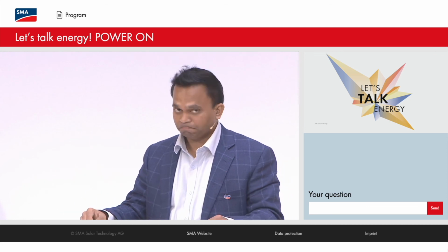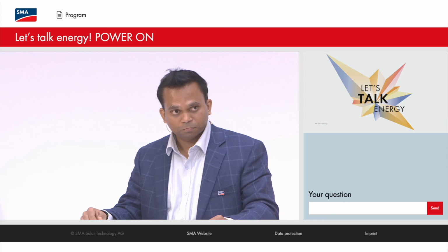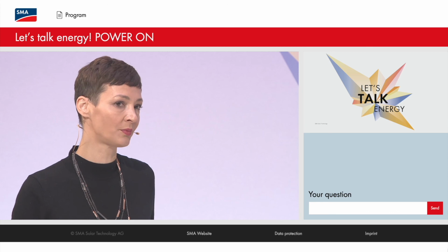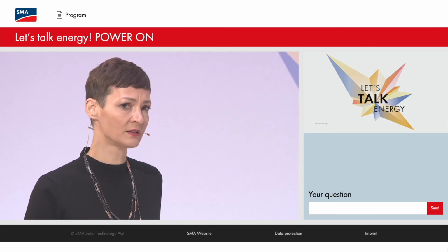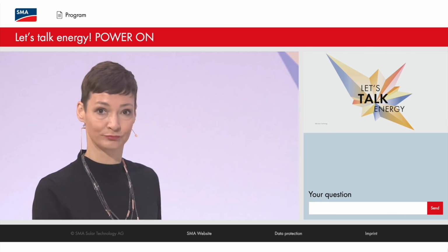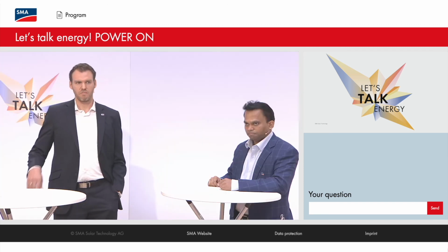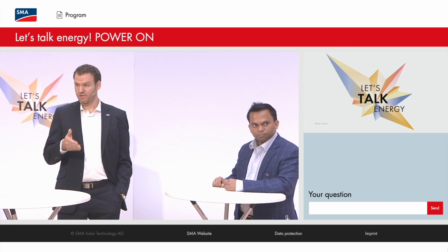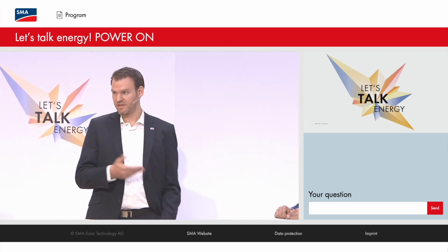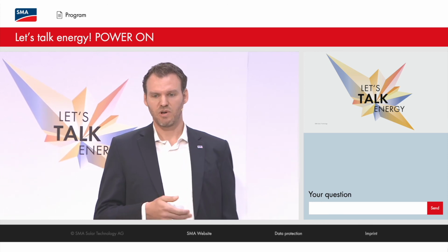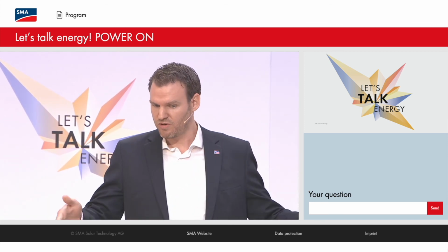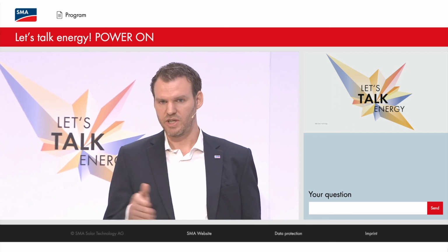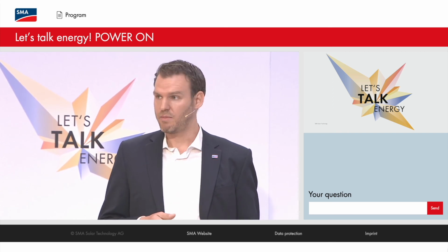Okay. We have 45 seconds for the last question. What is the SMA solution to minimize the downtime of central inverters when a component fails in the inverter, meaning losing a lot of revenue? Of course. That's a fair point, and probably one of the major criticisms around central inverters. There's pros and cons with having fewer units. One is obviously when one fails, there's more energy loss. At the same time, you have fewer service actions, because more units means also more service tickets, more actions to go to site. So it's a bit of a comparison of yield or availability versus labor cost.